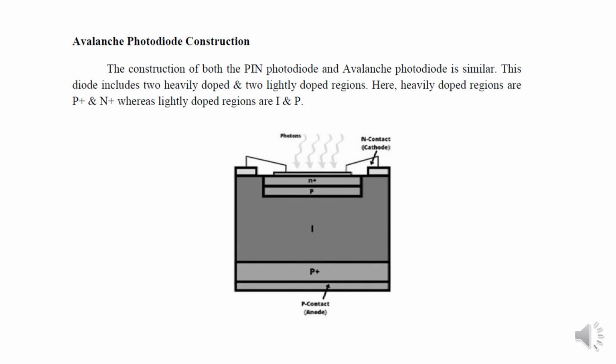In this type of operation, the photodiode can be operated above the breakdown voltage, and the other mode is namely sub-Geiger mode. Also, for the working principle, the avalanche breakdown occurs mainly once the photodiode is subjected to maximum reverse voltage. This voltage enhances the electric field beyond the depletion layer when incident light penetrates the P plus region, and then it gets absorbed within the extremely resistive P region, and therefore electron hole pairs are generated. Also the charge carriers drift, at saturation velocity, to the P plus region, where a high electric field exists.